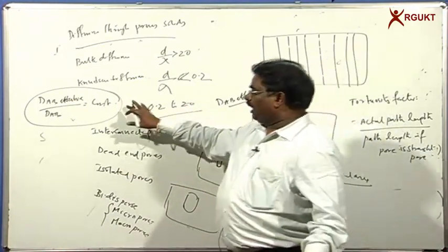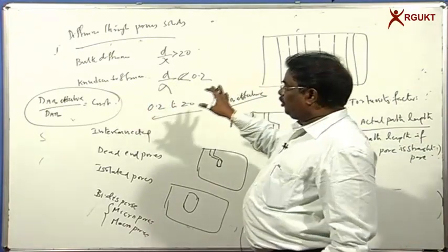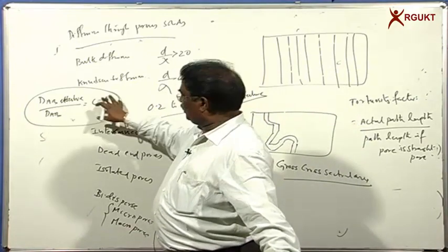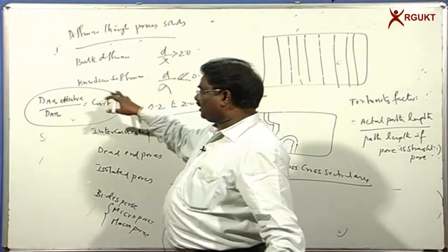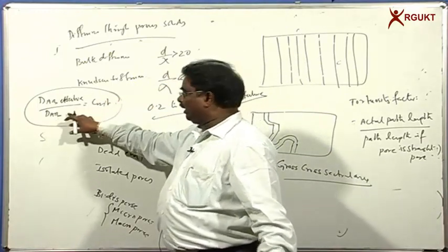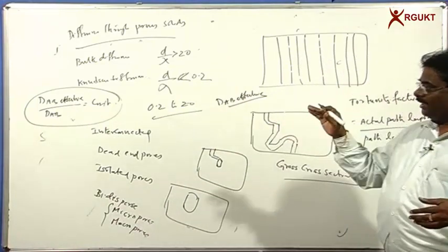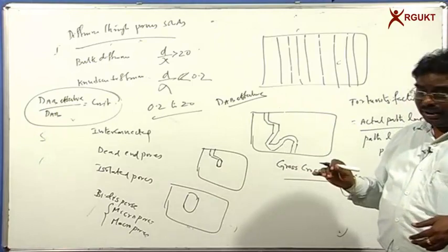For example, if I perform some experiments with a given membrane, I am able to find out the value of DAB effective by DAB. This will be a constant. When I am working with some other system, this constant again will be equal to DAB effective by DAB. So what I want to tell you is that the DAB effective will be smaller than the actual DAB value. However, DAB effective by DAB is equal to a constant.